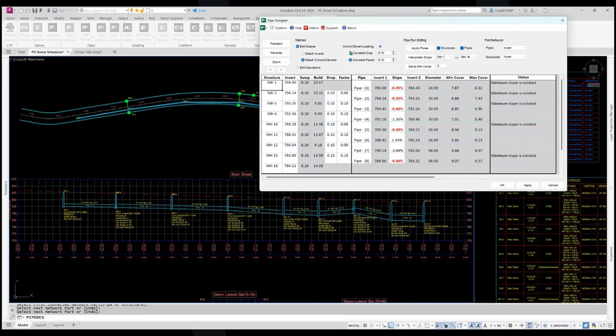And it's going to calculate the end elevation of the outgoing pipe. That's based on a formula that you can find in the help manual if you want to see it, but it's simply pipe elevation 1, incoming and outgoing pipes, and then subtracted by the drop plus the factor.